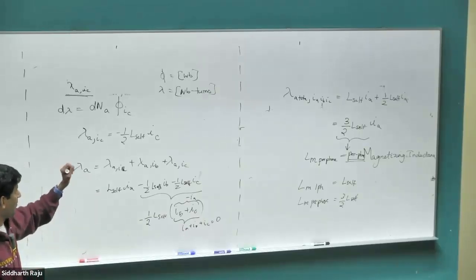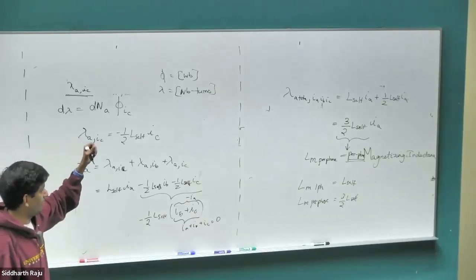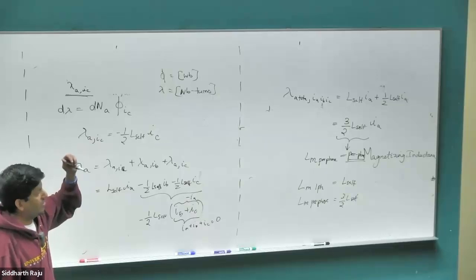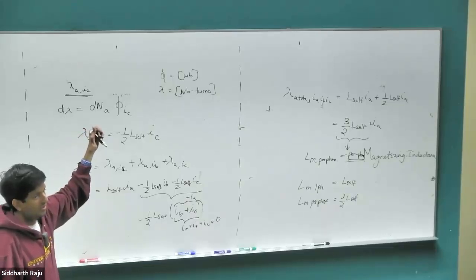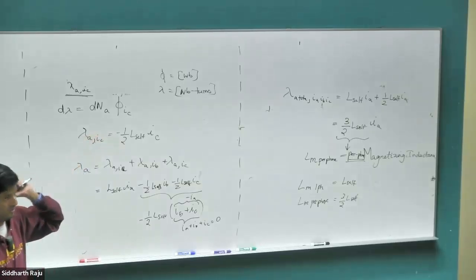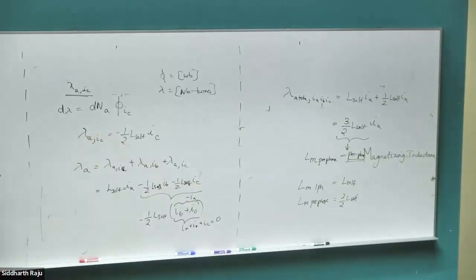It has a significant physical meaning to it because it's the flux linkage. When you measure the EMF, it's actually measuring the effect of lambda. It's not measuring the effect of phi directly. It's the lambda that matters. Any other questions?